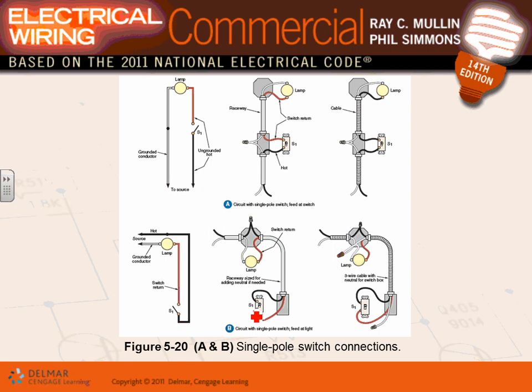Here's the schematic for it. Here's the real wiring. I have a conduit. I brought the hot and neutral, black and white, into the box that has a receptacle. What you did, guys, is you brought the hot into the receptacle, supply and return goes into the light. So the switch return is your red, black, red, going all the way back. Now if you have a cable, it's the same thing. Can you guys see that?